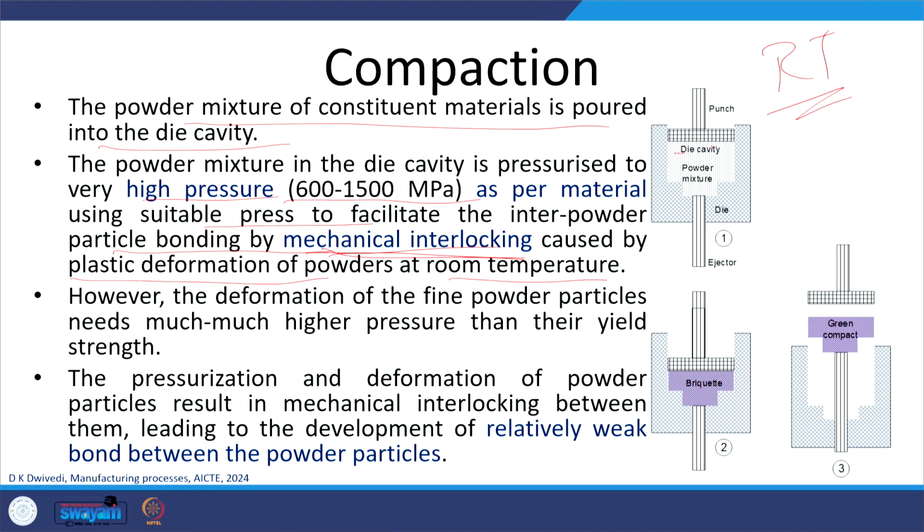Say this is the die, this is the punch, and the powder particles have been filled in this die. Then it is pressurized. When it is pressurized, the porosity between the powder particles is reduced. The voids and pores between the powder particles are reduced, and it forms the briquette or the green compact. Then this is taken out.